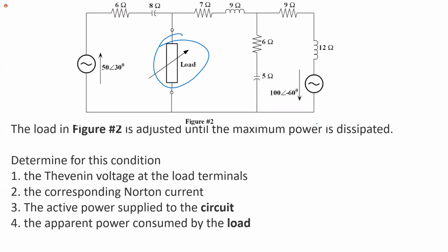So we can find R Thevenin by opening the load. We're going to talk differently, because if you look at the circuit you have inductors and capacitors, right? Yes, sir. What you're finding is Z Thevenin. Oh, okay.